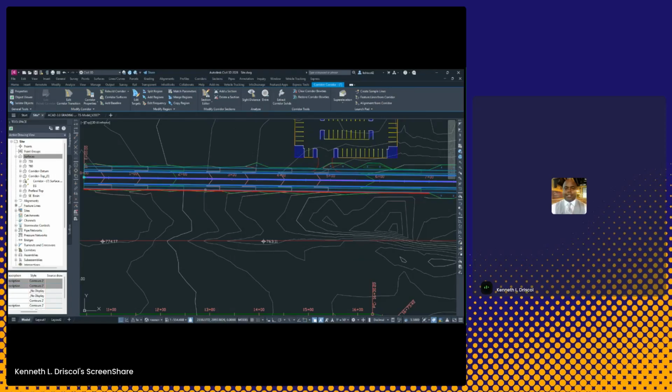If I pick on this, down at the bottom, it says select the feature line or select all. I select OK. It shows me all the way to my sidewalk, and I just select OK. Now from that, here's my feature line.